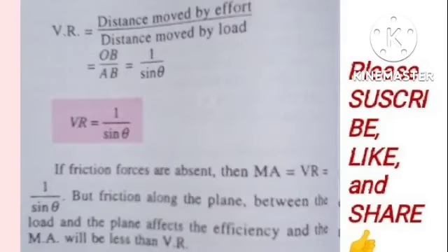Now this is the equation representing the relationship between the velocity ratio and the sine of the angle of an inclined plane. So here the velocity ratio is equal to the distance moved by effort divided by the distance moved by load. So the distance moved by effort is basically the surface of the inclined plane through which the object moves. But the distance moved by load is the vertical height through which the load is raised. So that means that if you look at it from a trigonometric standpoint, that is the inverse of the sine of the angle of the inclined plane.